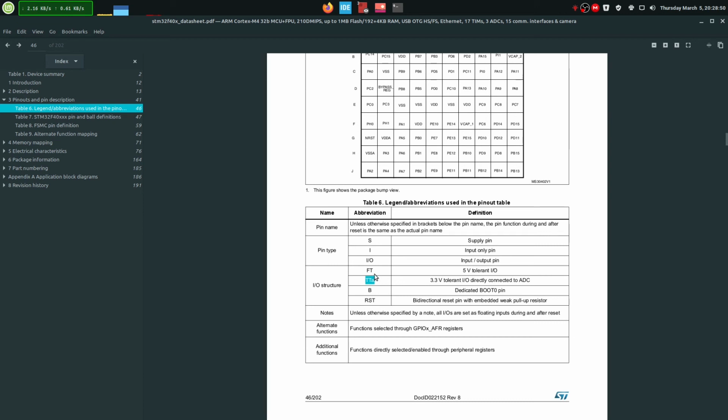So if you're using some kind of peripherals outside that are 5V, but your processor runs at 3.3V, as these do, then you're gonna need a pin that is 5V tolerant so it can withstand an input. A project I did required a 5V input that should be lowered to ground, so I was using the GPIO portion for the pin that needs to be 5V tolerant, and I'll show you later what happens if you do it on a pin that is not.